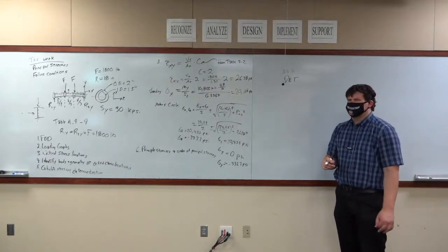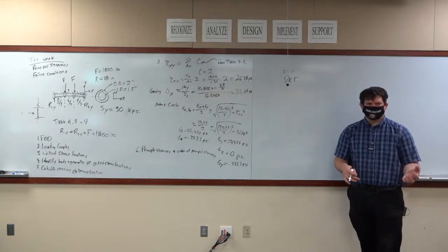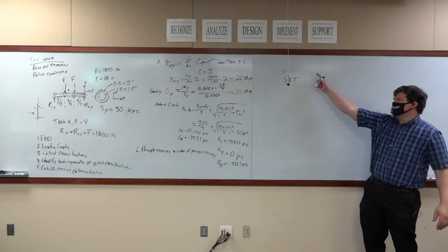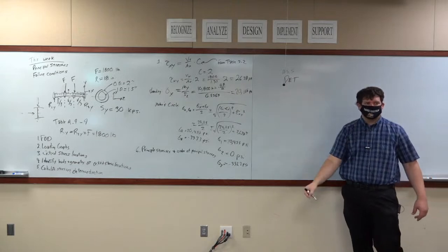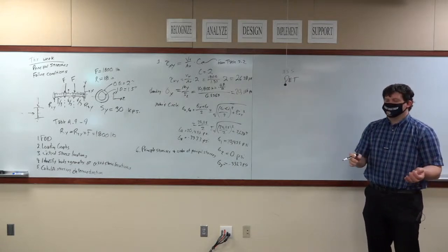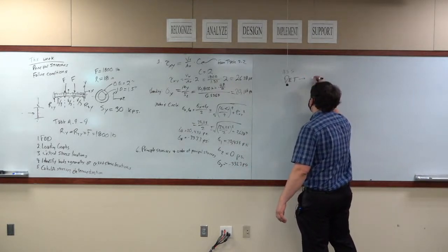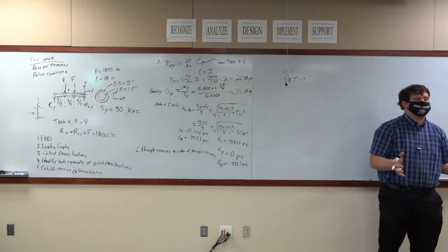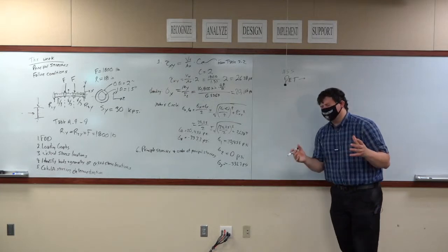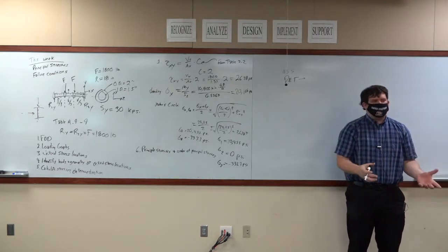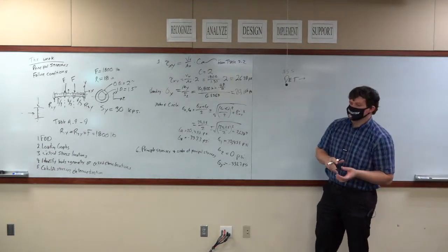You can also use the other one, the Coulomb-Mohr theory, but that takes into account the compressive stress, and you get the same equation as MSS using that way if both the compressive strength and the tension strength are the same. For steel, it has the same compression and tension strength, so we're not going to use that one. There's no reason to. We're going to use this one. This one uses von Mises stress, which if you've done SolidWorks analysis, you've seen a von Mises stress before. Basically it is a measure of the amount of energy that is being stored in a single unit element due to the loading conditions.